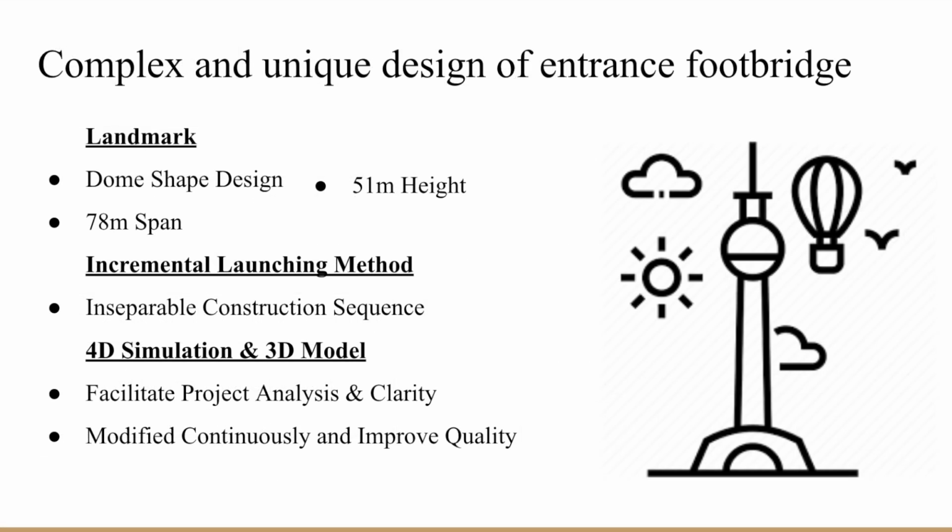The second challenge is the complex and unique design of the entrance footbridge. The developer aimed to construct the bridge as a landmark. The bridge adopted a dome-shaped design with a 51-meter height and 78-meter span. The bridge also adopted the incremental launching method due to environmental concerns.